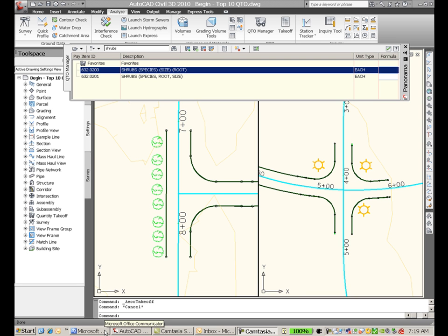One of the top features in AutoCAD Civil 3D for transportation engineering is the ability to calculate quantities, something also known as quantity takeoff. Without the automated approach, this would need to be done manually, counting items paid for individually, like lampposts, and performing measurements to get quantities of other items, such as linear feet of curb and gutter.